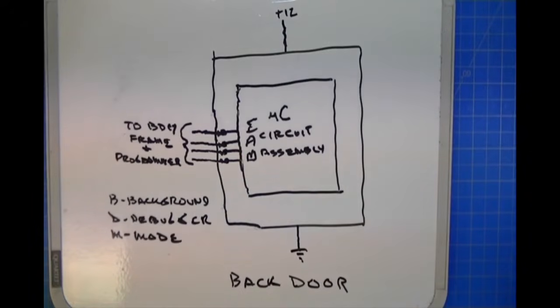So they would write little chunks of their code, upload it to the RAM, test it out, and get it working, and then write another chunk, upload it to the RAM, and get it working. By the time all of their chunks of code were working properly, they would link them all together, program all of that into the program memory of the microcontroller, and then test it to confirm that it worked. And that's how it was done initially.